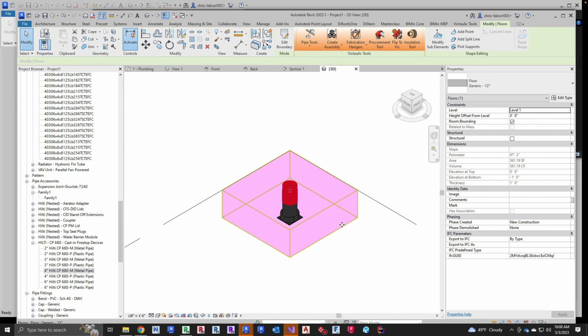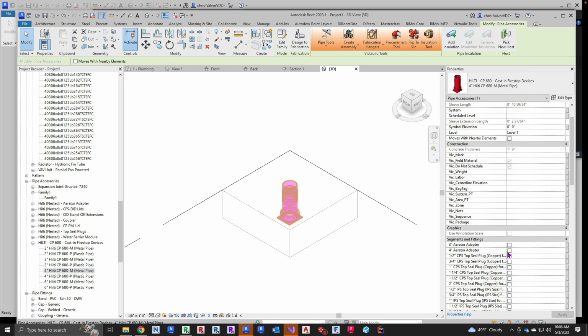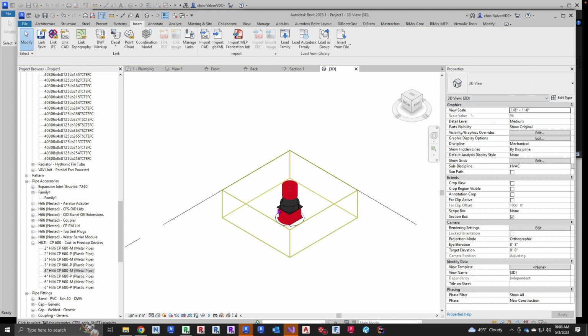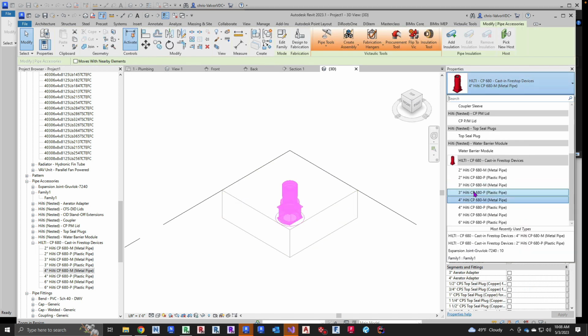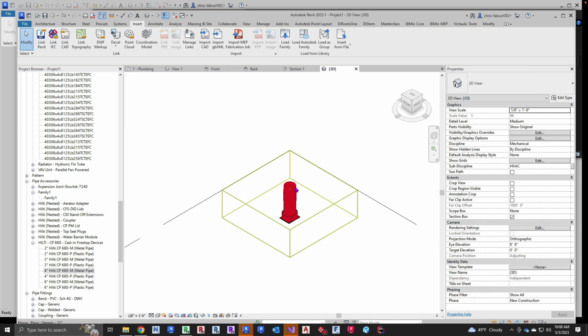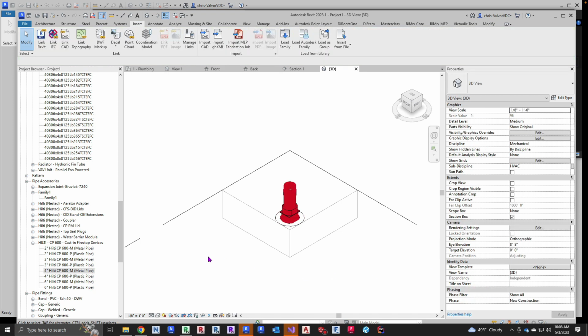When you look at a lot of our sleeve schedules for the Mather, it says has aerator. It has a check because it has an aerator. The ones that don't have an aerator don't have a check. And like I said, I built it to where it only puts a 4-inch aerator on a 4-inch sleeve, a 3-inch aerator. So if I was to come in here and change the sleeve to 3-inch, the aerator disappears, but now it works with the 3-inch. Yeah. So I built different things so that it'll run different ways.